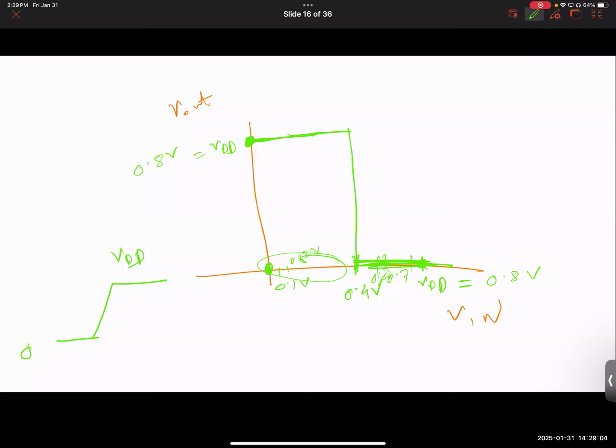No, I'll gradually charge up my input from 0. So I will have all the other intermediate voltages. What happens then? What happens for VDD over 2? There will be situations where both NMOS and PMOS will be on momentarily, but hopefully not for too long, but for some time, they will be on. So it's not perfectly ideal as we hoped initially.